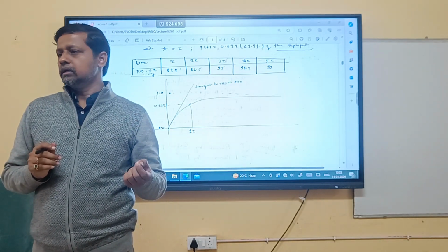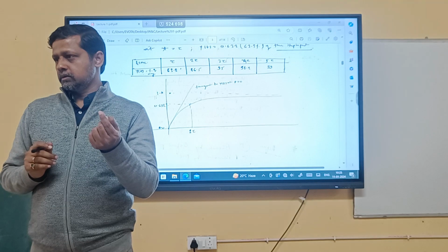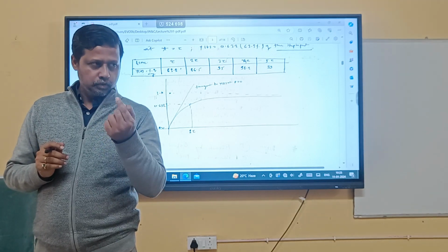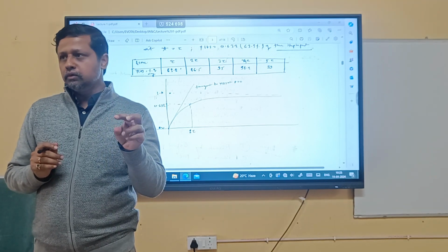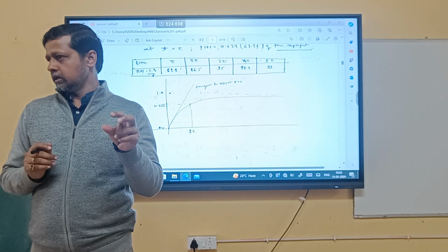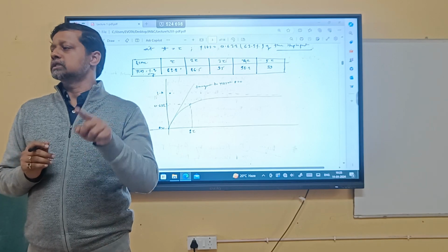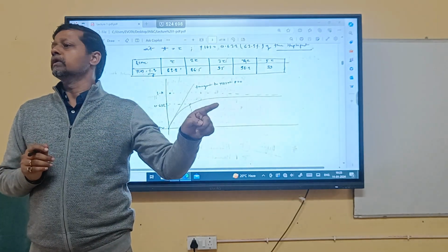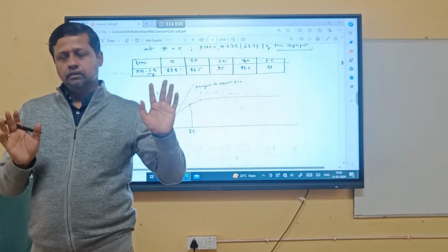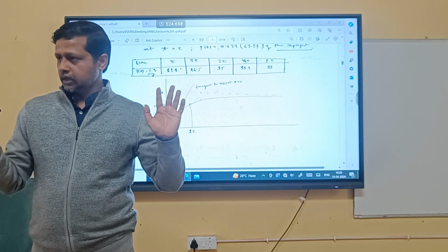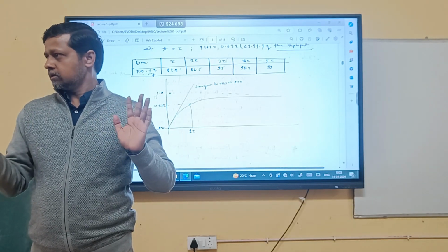How are you able to detect it? Because this 1 is fixed, 1.5 is fixed, 2 is fixed. So if I tune my radio, my tuning circuit, at 2, it will pick only that particular signal, not the one available at 1.5. Is it correct? Any deviation in discussion?